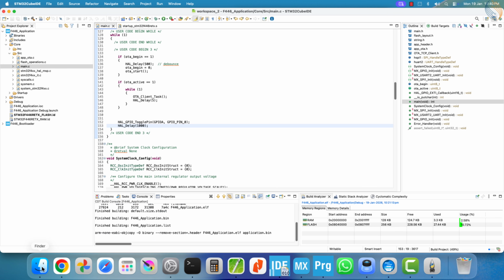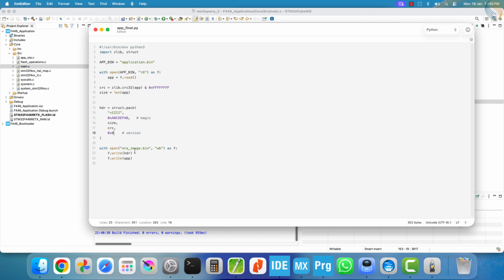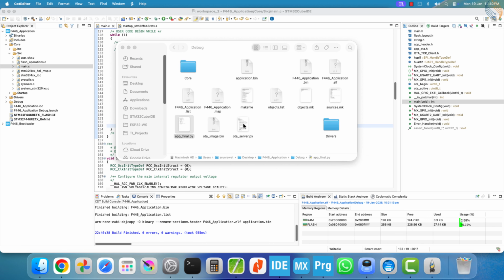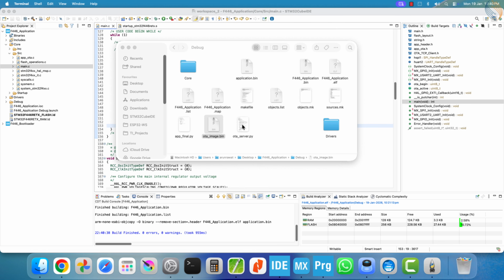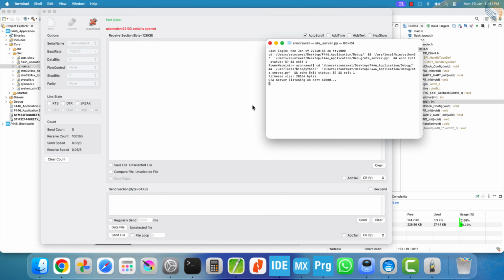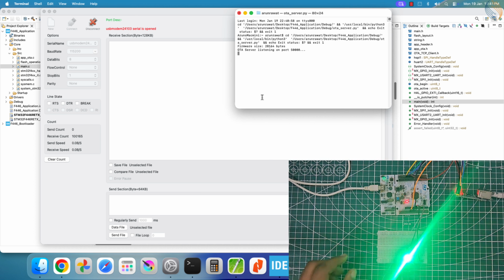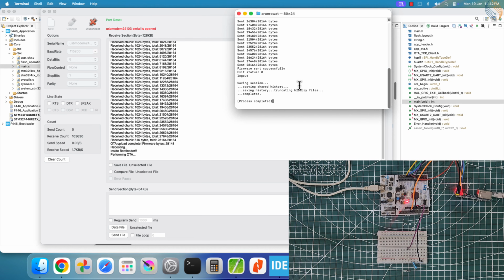The entire process is now almost fully automated. There is no longer any need to manually insert the CRC or firmware size into the application, or copy a generated OTA header file into the bootloader. The application downloads the update, stores it in flash memory, and then reboots. The bootloader verifies the update, flashes it, validates the new application, and jumps to it. The only remaining task is to define how the OTA process should be triggered. In this video, I used a button as the trigger, but you can implement any other trigger mechanism based on